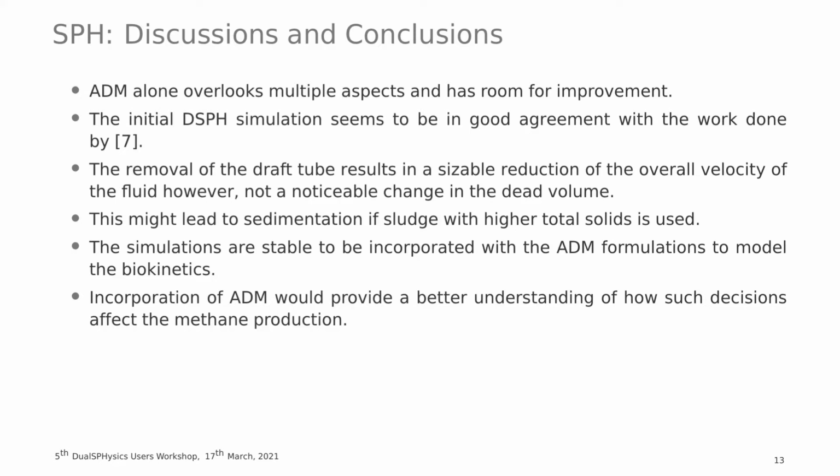But we need to be sure. I need to point out that this is not harmful as long as we do not use fluids with a higher total solids, which the authorities have started using. After the removal of the draft tube, they don't use sludge which is prone to sedimentation, and we feel that the simulations are stable enough to be incorporated with ADM to model the biokinetics, which would allow for a better understanding of how such decisions affect the methane production.